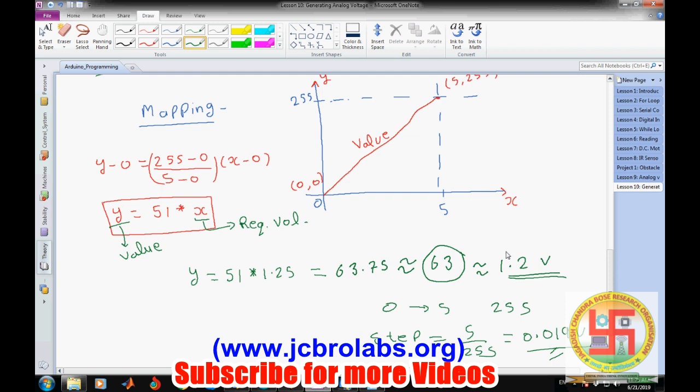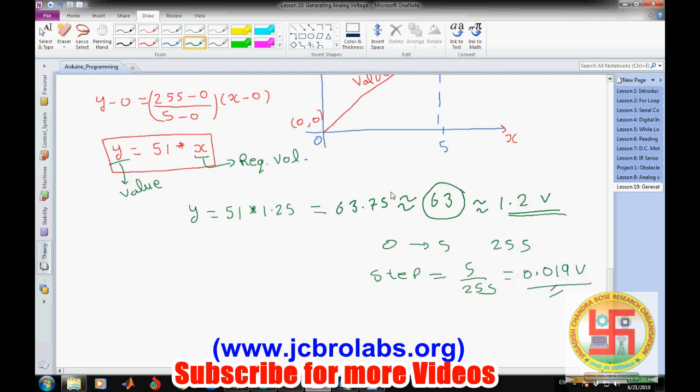So these are the theoretical values. Now we will check on the Arduino whether we are getting exactly the same value or not. I hope you are familiar with the concept of how to generate values and what the resolution size is, because we can have only 255 numbers for a range of 0 to 5. Now let's write a small program and then we'll check how much value is generated.